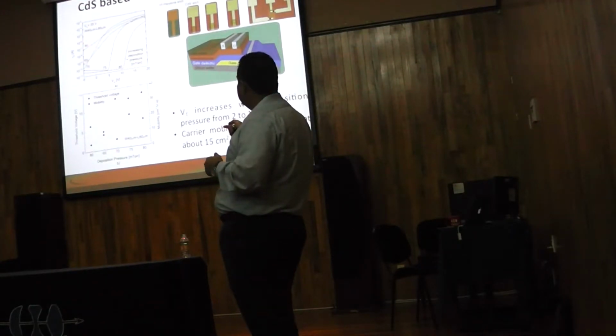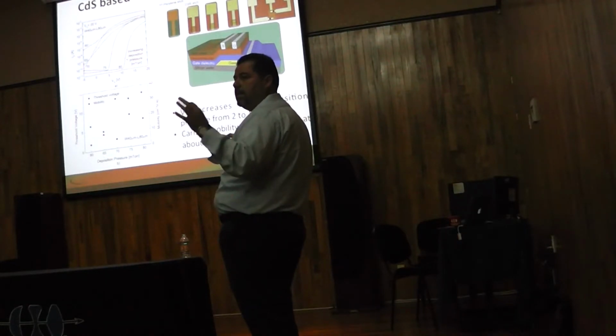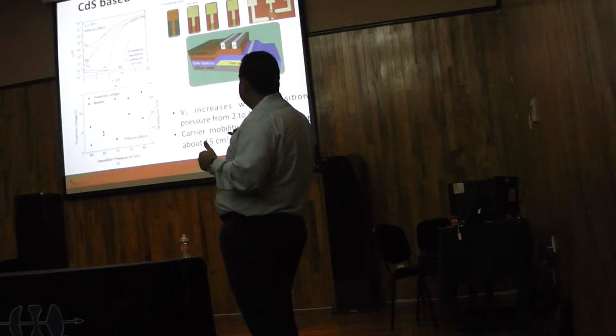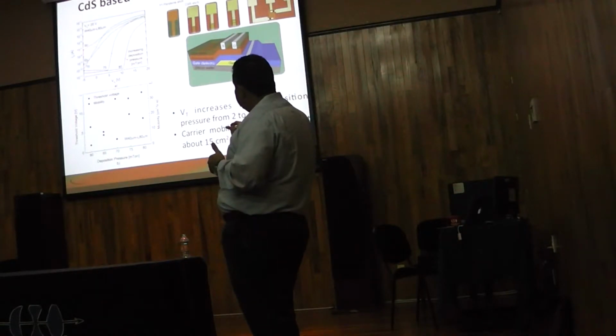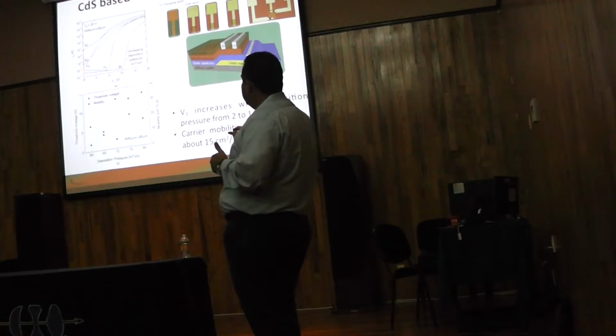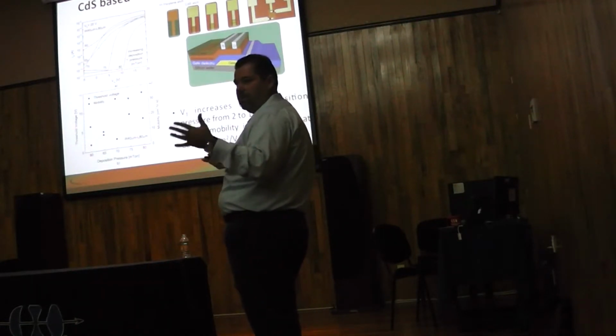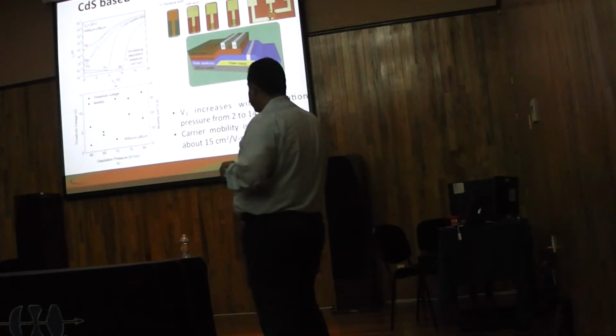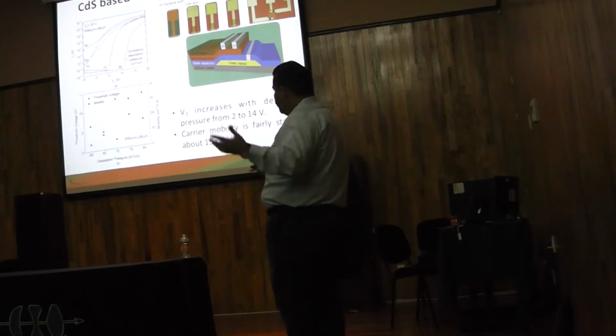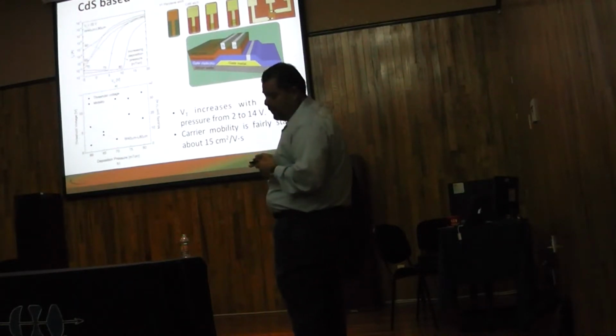So in the deposition pressure, you can see that as you go from lower pressure to higher pressure, the transistor becomes better and better. Okay, so these are experimental results from the measurements of the transistor. The films that are more conductive, the 60 millitorr, the I off is higher than the others because it's more conductive. So it's more difficult to turn the transistor off. And then we extract all sorts of things like mobility, threshold voltage as function of pressure.